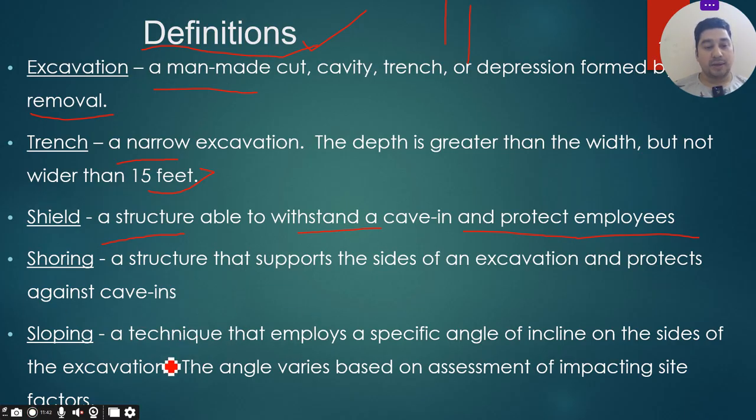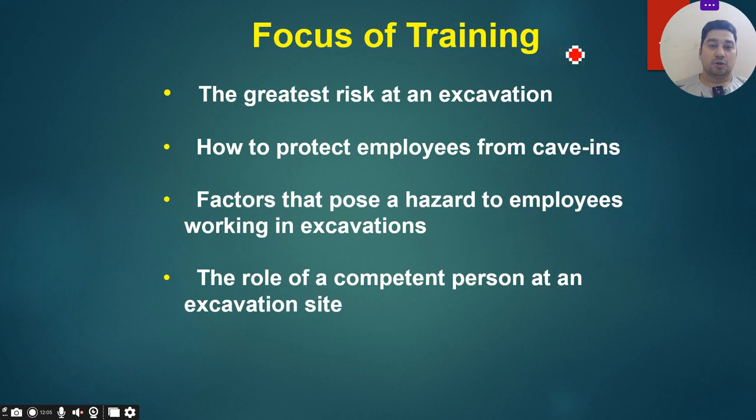Then sloping. Sloping is a technique that employs a specific angle of incline on the sides of the excavation. The angle varies based on the assessment of the impacting site factors. So with sloping, you will go down at an incline, like this. So those were the definitions.